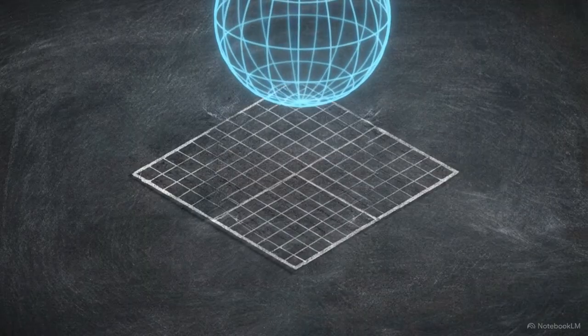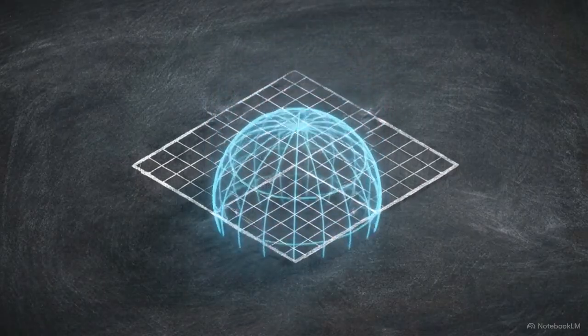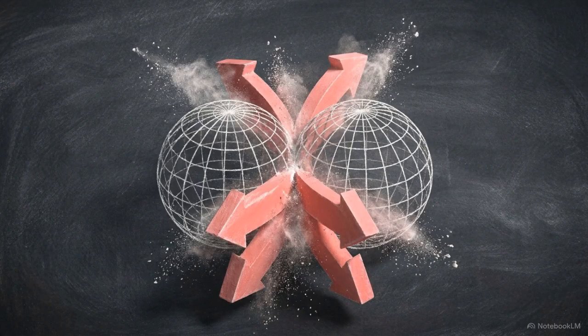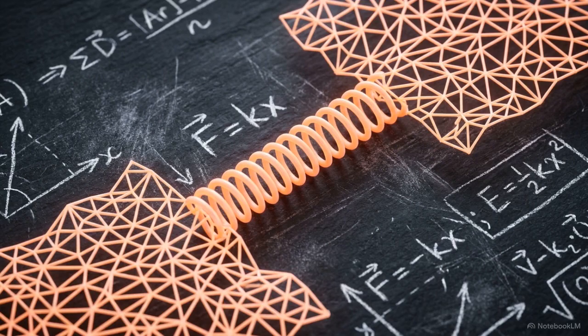The solver lacks geometric awareness to identify when parts occupy the same space. Without instructions, the meshes simply clip through each other. If the solver does not recognize that a collision is occurring, F contact remains zero, the meshes penetrate, and the simulation loses physical validity. To maintain the loop, the solver must generate a repulsive contact force the moment meshes begin to overlap. This requires specialized algorithms that bridge the gap between abstract matrices and physical boundaries. Calculating F contact is the necessary transition into the final layer of crash dynamics, the penalty method.